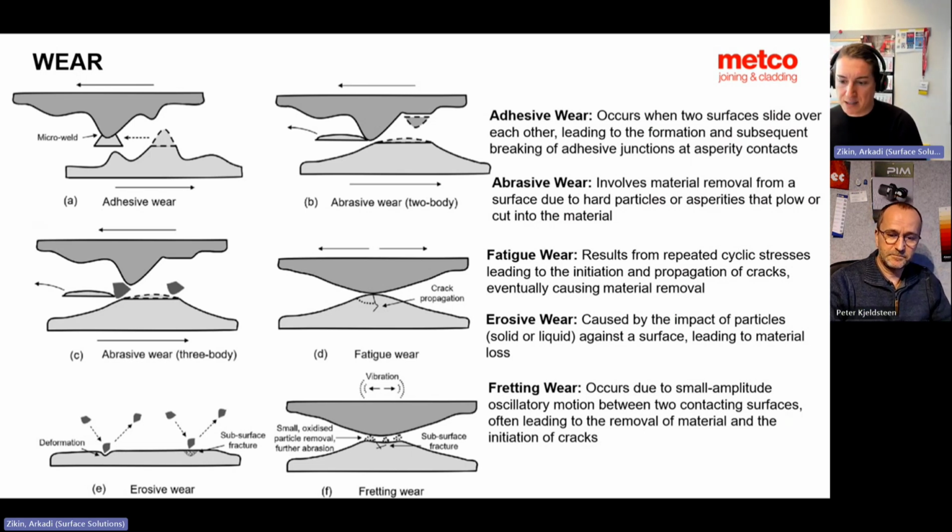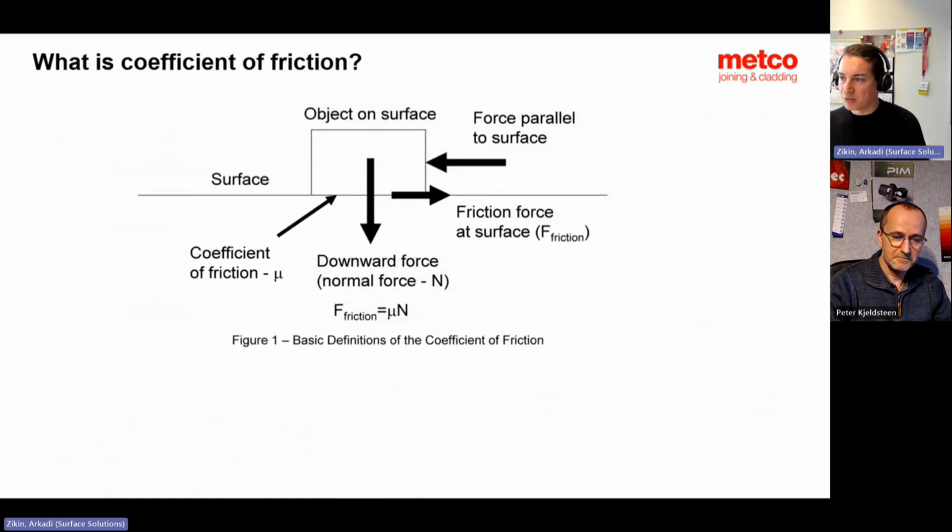And let's be very honest, we quite commonly work with two different coatings. We apply a so-called soft layer, we call it a buffer, something ductile. And on top, we apply something very hard, which might anyway already have cracks inside due to residual stresses and also typical cold cracks. And then you don't care about those cracks as long as you don't have, for example, impact or high erosive wear under, let's say, a straight angle. And that's a difference. So we move on.